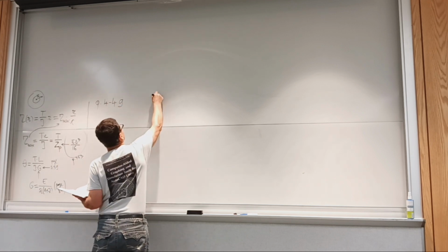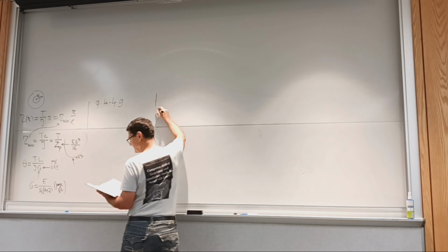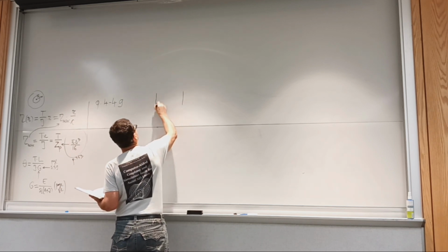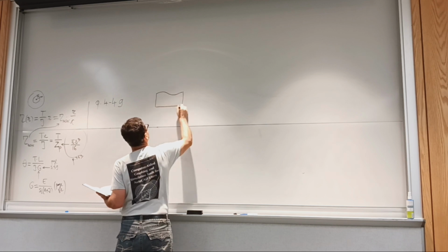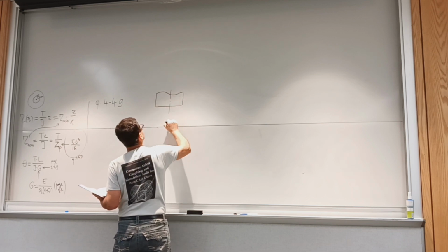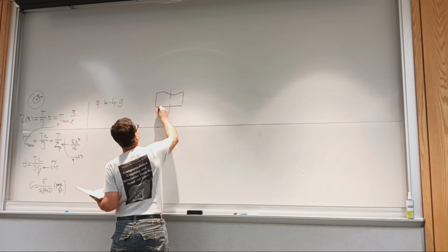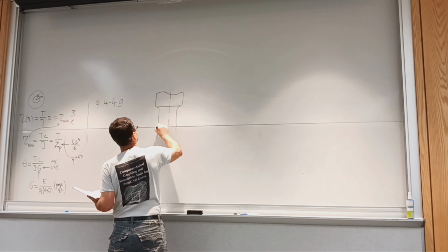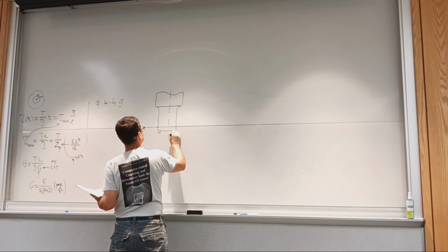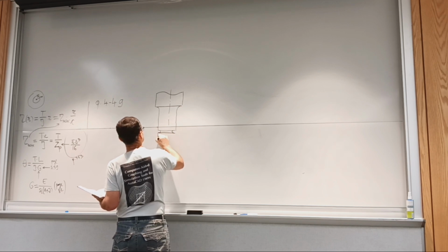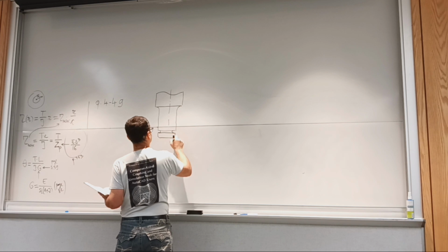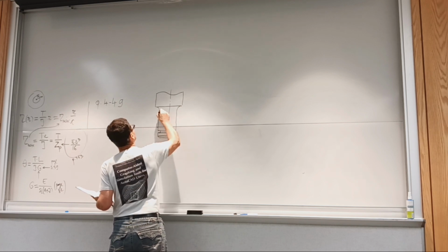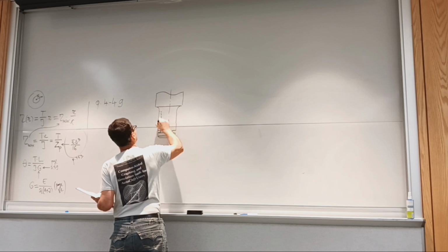So 49. And so we have, let's draw just the shaft, forget about the actual blade. So we have the axis of symmetry, and then we have the step with the fillet, and then it goes to a groove, and then it's the end of the shaft with a chamfer. Usually you want to have that chamfer. And then there's the profile key.